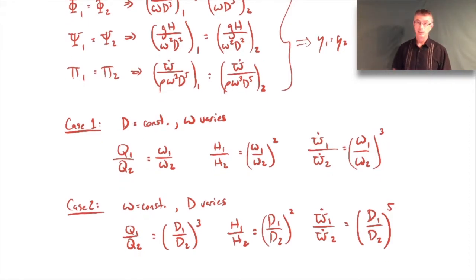So again, we have from the manufacturer our pump performance curve for a particular single impeller and a particular rotational speed, but now we're going to replace that impeller with one of a different size. And so this would be a way to predict the performance using that new impeller for the same rotational speed. Now, the prediction using this is not all that great. I mean, it's okay. It's good enough for a back of the envelope calculation, but it's not that great.